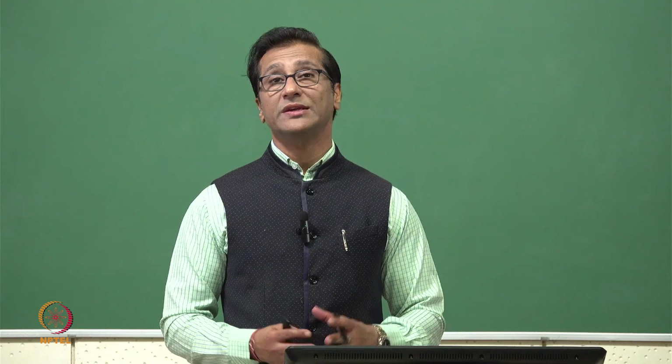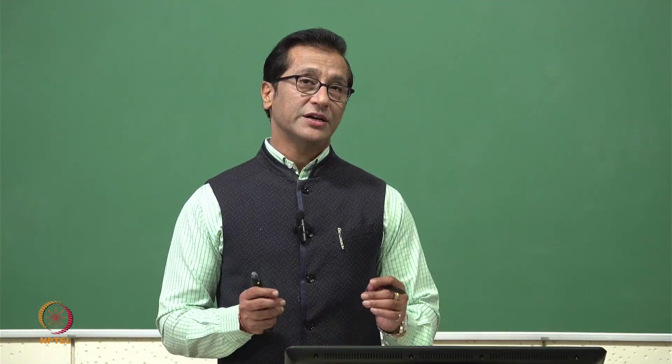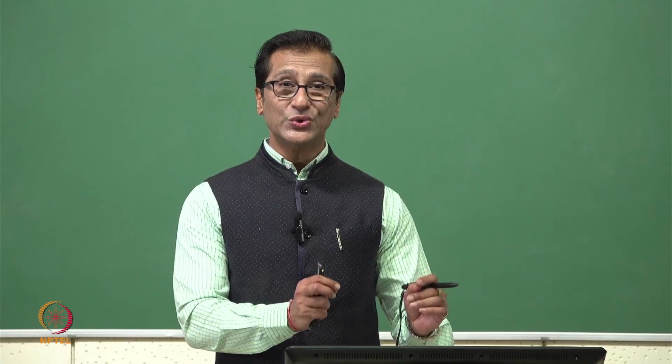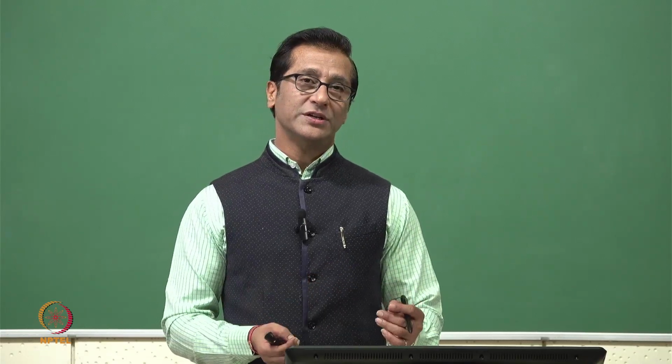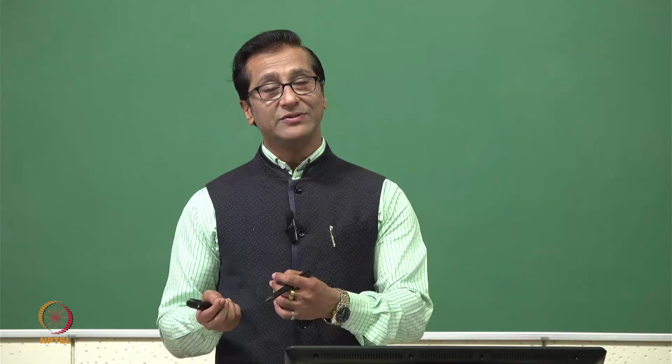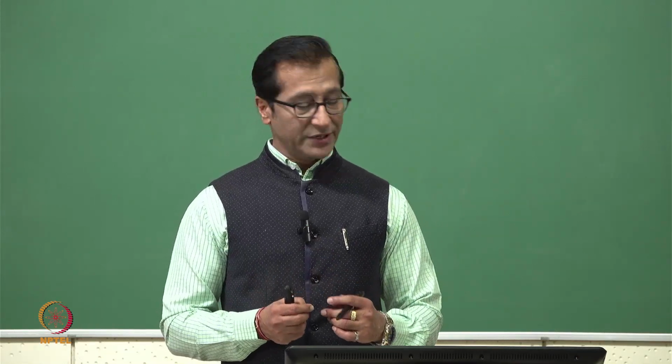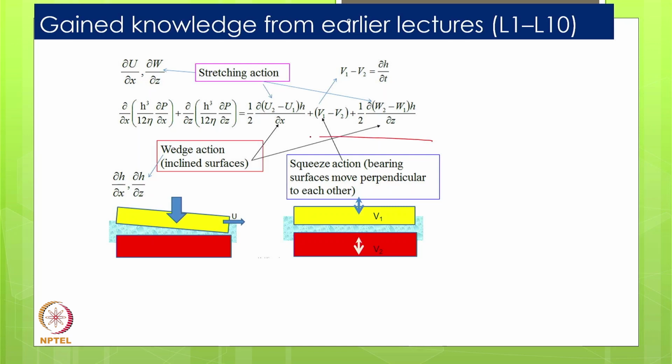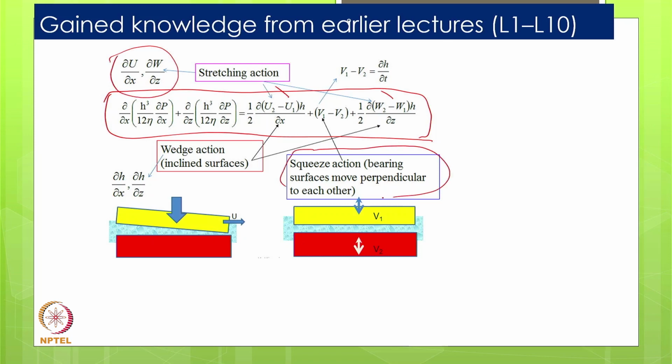Now we talked about elastic deformation, but the lecture title itself is elastohydrodynamic. So we cannot omit the hydrodynamic action. We already have discussed elastic action, but now hydrodynamic action. Earlier, in a previous lecture, we derived, or maybe presented, the Reynolds equation, and various terms were defined, the u value and the b value. This is what we also call a stretching term. We also described something like a squeezing term, the squeeze-out term, and then we also said that for hydrodynamic action we really require a wedge action.